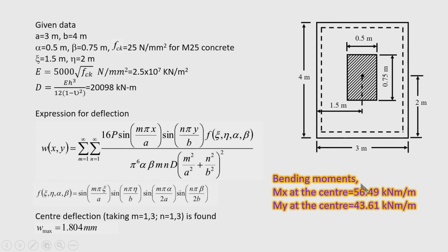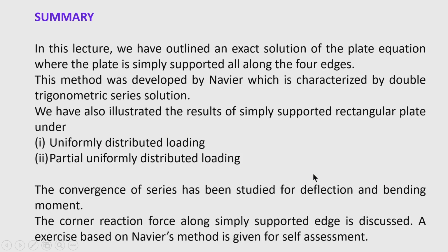Okay. So, let us summarize what we have done in today's class. In today's lecture, we have outlined an exact solution of the plate equation, where the plate is simply supported all along the 4 edges. Actually Navier's method is an exact solution, and it is a very well known analytical method used everywhere.